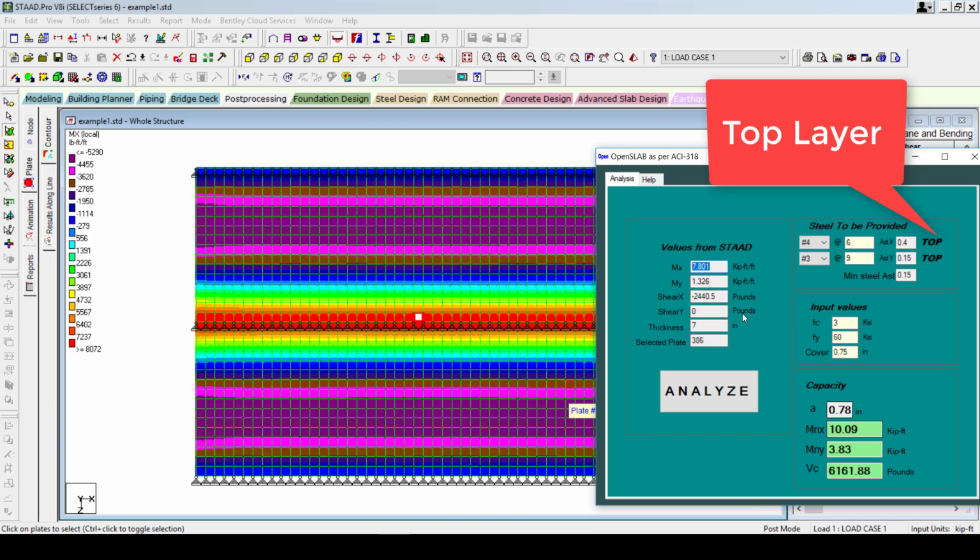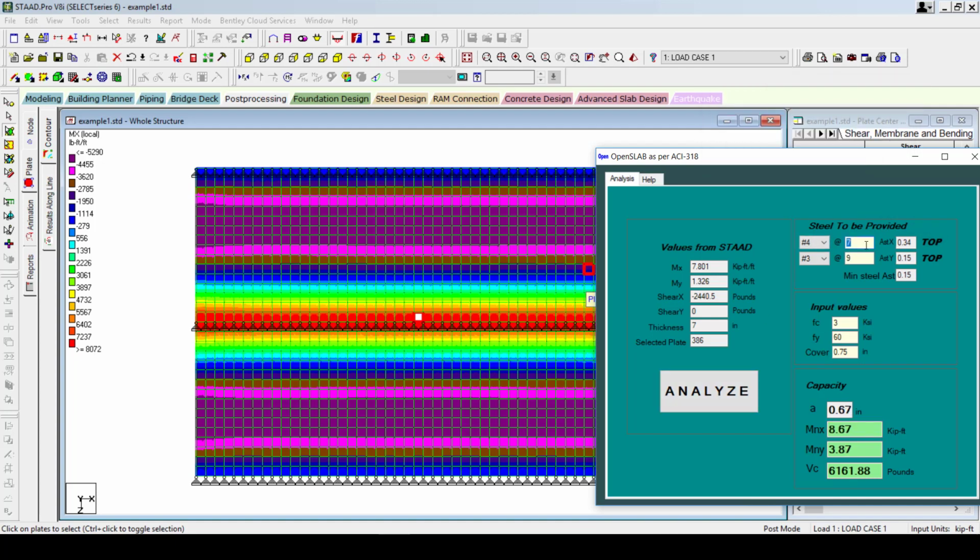And we have our steel sufficing. So now for the continuous, I think I'll go with number 4 at the rate of 8 inches. No, it's not working. It's going to be 9 inches. 7 inches maybe? 7 is fine, but since it's 7, I like to keep it 6. So yeah, that's fine. So what about this span? I should be having the same results.